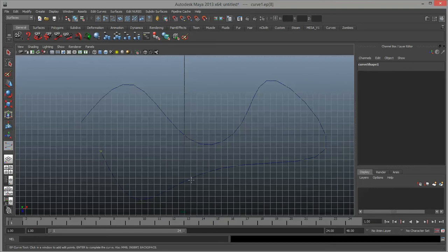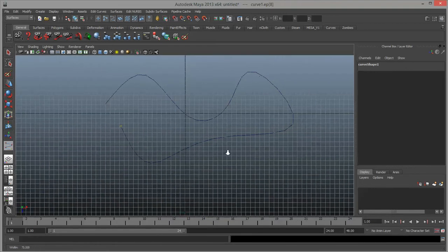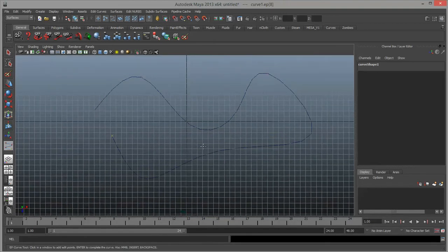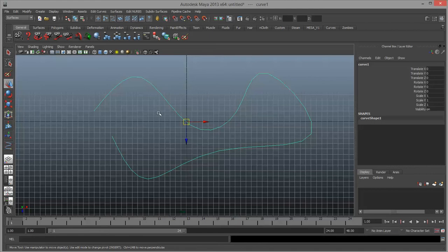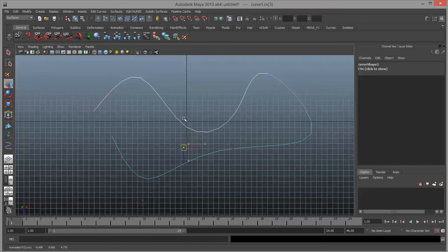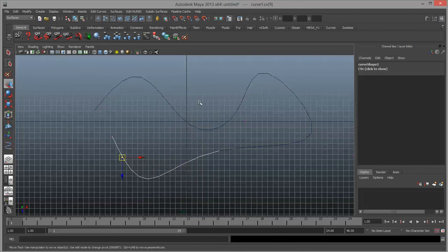They're really just points that reside on the line, and the line is flexible. When you're done, hit Enter. You'll have the same sort of line created as before. And if I right click and hold Control Vertex, we again get control vertices that are off the line. That's just the way that we interact with these. Okay? But the same sort of line is created, so you can use either one of those interchangeably depending on your preference.